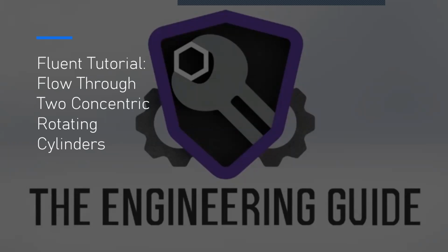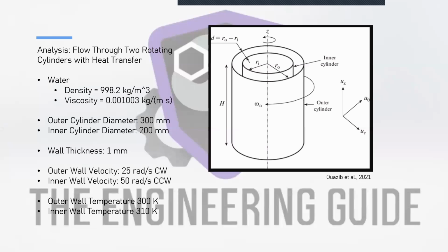Today we're going to be doing a Fluent tutorial, which is the flow through two concentric rotating cylinders. Let's get into it. As I mentioned, the analysis that we're going to do is analyzing the flow through an annulus that has two rotating cylinders with heat transfer through its walls. We can see a diagram to the right of what this looks like. So we're going to have two cylinders here, and we are going to be analyzing it in 2D. We're going to be taking a cross section of this geometry.